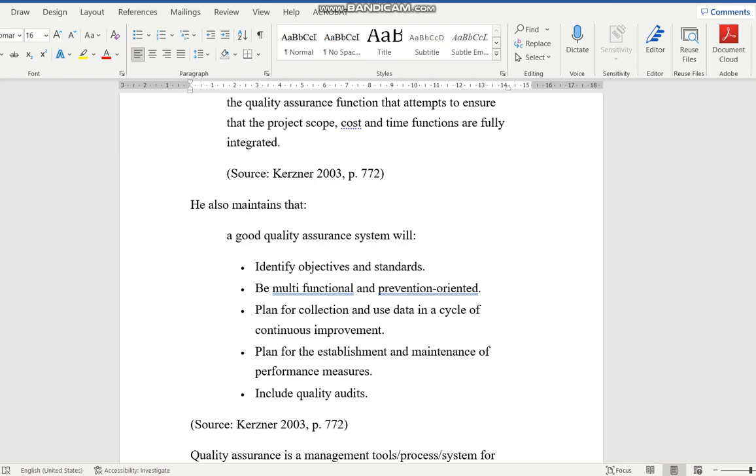And then, for example, concrete. To check the fluidity of the concrete, the flow, you need to make sure that it flows. It's a ready mix, so that flow must be just nice. It cannot be too thick, it cannot be too thin, see? If too thin, then the aggregates and the water will segregate, and it will end up too layered. There'll be some layering in the concrete at the end of it. But if it's too thick, it doesn't flow, you see? The fluidity is not there. So it's not good for working in that sense.